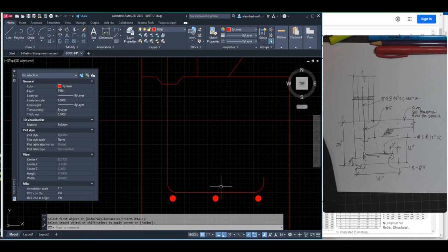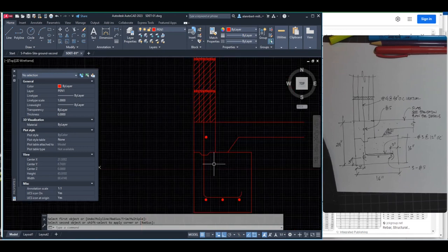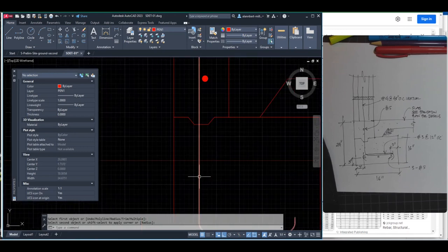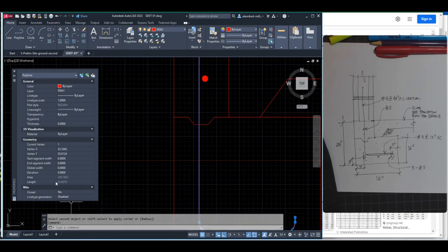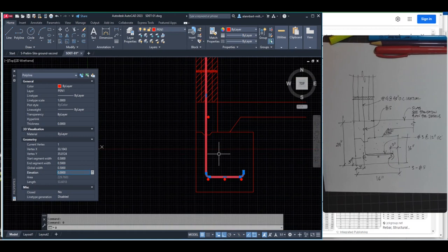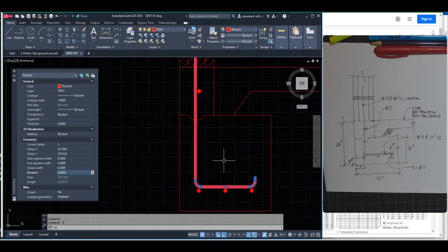There you go. And then we want this to be thick, so I'm going to click on this one, and I will change the global width over here to 4, number 4, which is 4/8, so it's half. So I'm going to put in 0.5. Press enter, and there you go. 4/8 is 0.5. Okay.